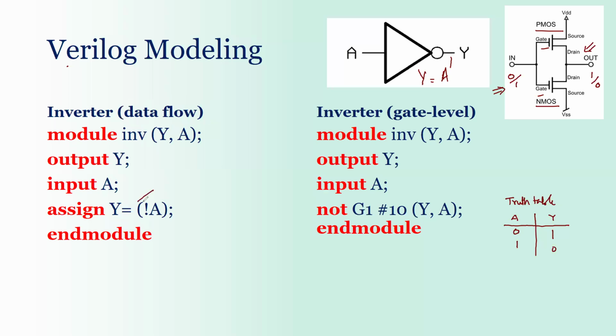Here you can see that this command can also be written as assign Y, and you use this sign instead of the exclamation sign. This sign can also be used in Verilog. Okay, so that's your data flow modeling.